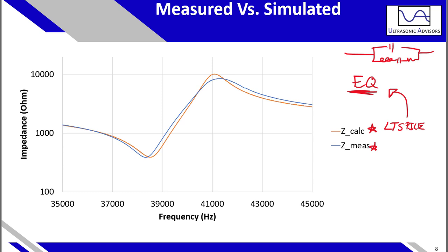and we are then comparing that to the measured value, so the actual values measured. We see that first of all they do match. Actually, when I found that 2 pi error, that I didn't put 2 pi for the angular frequency when calculating the parallel capacitance, the way I found that was this was way off. It did not even match up at all. So that's one nice thing: always compare your calculated and measured results, the result of those parameters in comparison with your measurement.